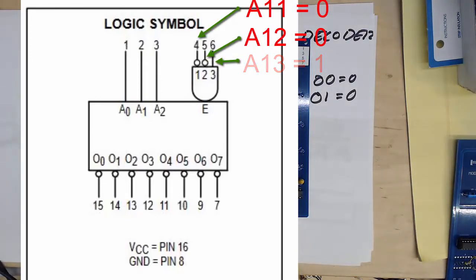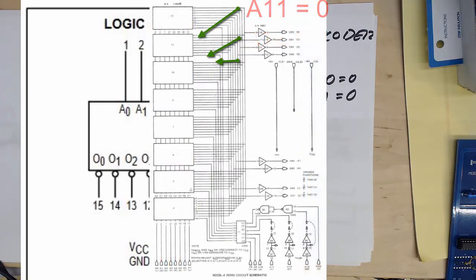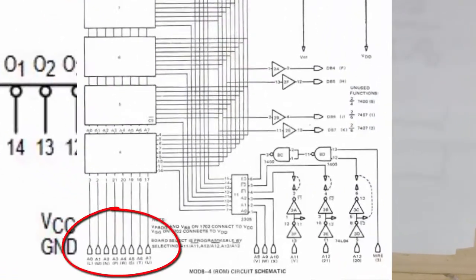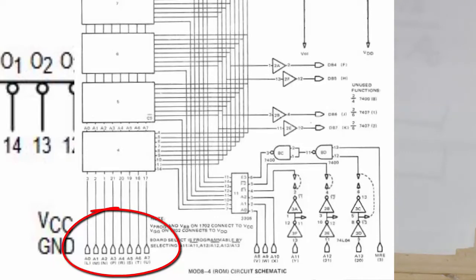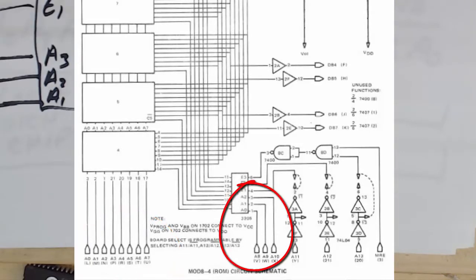And we can see on the schematic where we have the addresses from A0 to A7 going onto the chip, and that just continues and goes on up through all of the chips. And then we have addresses 8, 9, and 10 that come into our 3 address selections on the 74138, A2, A1, A0, and in this it's a 3208, which is the same pinout and the same function as the 74138, which is just more available now.